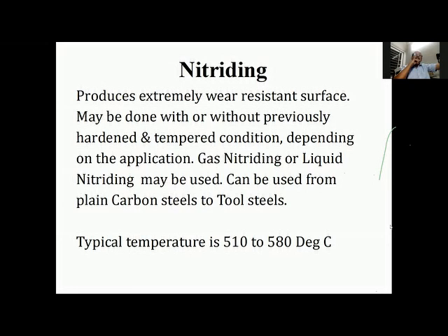Nitriding is an extension of what we discussed. It can be done with or without previously hardened and tempered conditions, depending on the application. Where you need good core properties, those can be provided by having a pre-hardened and tempered condition.